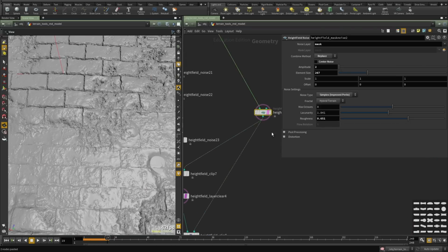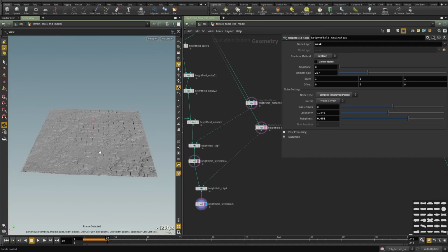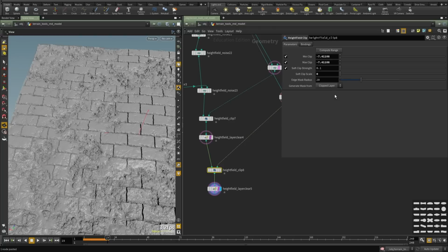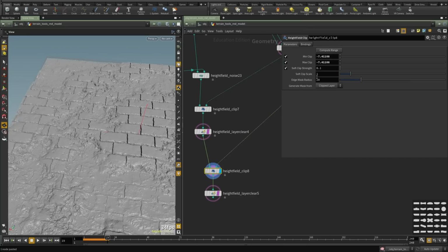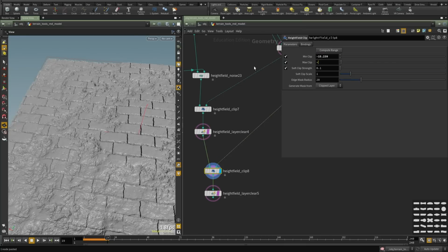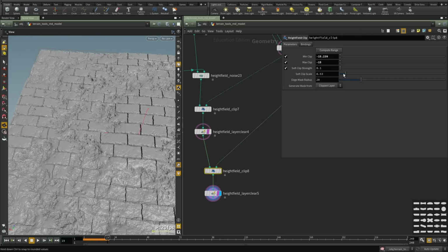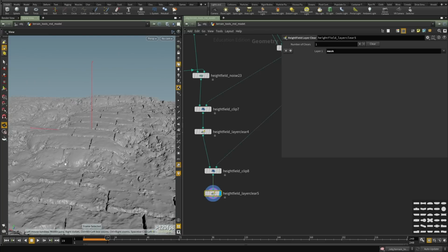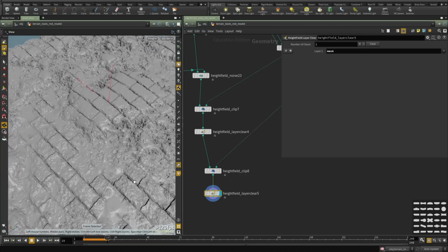And this is, yeah, this is the main effect I was looking for, but I like what we just did. And I'm going to generate another mask. I don't want the same one. And let's try 3. Very cool. And with this clip now, I want to set the clip to 0. Let's compute range again. Okay, so minus 15, because everything got pushed. And let's try. Okay, cool. Yeah, this is what I was looking for. I wanted to flatten these areas, and I have that now.